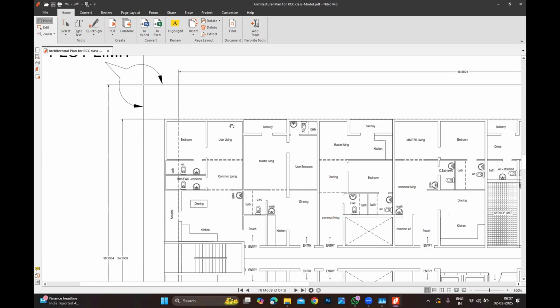Because finally, when the project is finished, before awarding, you will source the contractors, right? Then you will start receiving the quotations. The quotation is based on what? Based on your BOQ. Architect people can easily escape. The reason is, if they propose marble, they can easily change to tiles if the cost is high. MEP people can also easily escape. If they propose first quality material, they will say the same spec I can get in a different brand. Structural, you only have two items, concrete and steel. Unless you play from the beginning, you cannot reduce it.